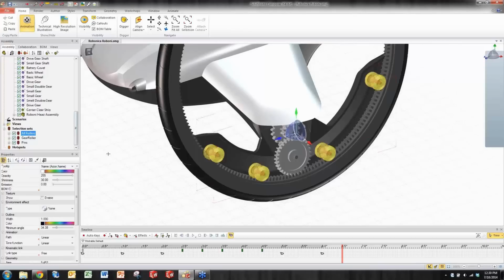So here, I want to use something that we call an effect. I want this thing to flash at the user so they notice it before I change its appearance to nothing. Under the effects here, we have 3 very popular ones called fade in, fade out, and hotspot. So here I'm going to choose hotspot. And in my animation, you'll notice 3 keys were automatically created. With these selected, take a look at the properties over here. Recognize which one is changing between these keys. Do you see which one it is? It's emission. Emission is going from 0 up to 1 and then back down to 0.